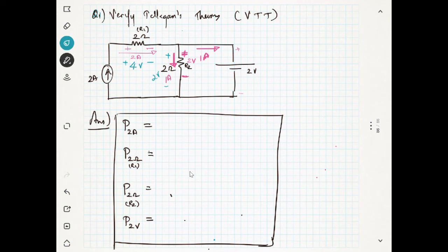We will write the Kirchhoff law to find this. I will just write the steps. So you can write the Kirchhoff law for this, KVL here. You will assign some polarity here. Say this is the voltage across the source, Vs. So I will write the Kirchhoff voltage law around this loop 1.